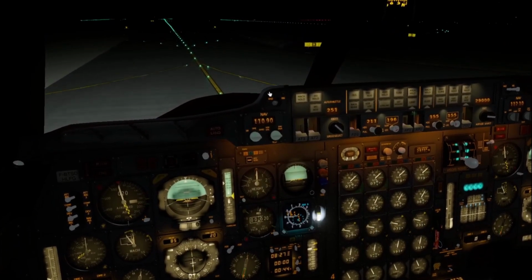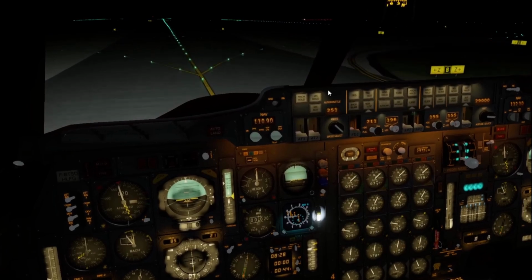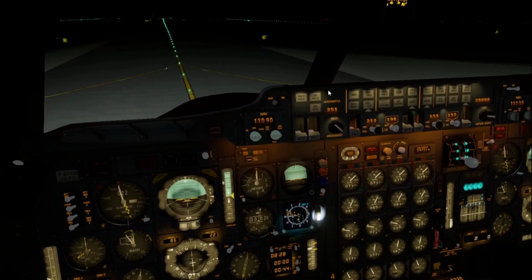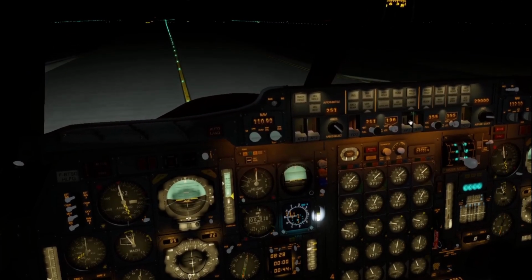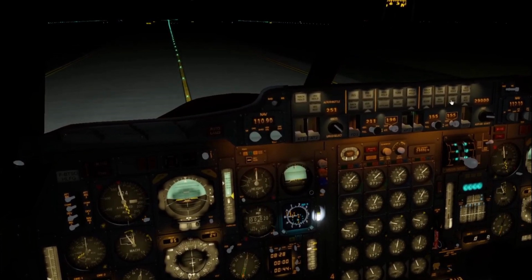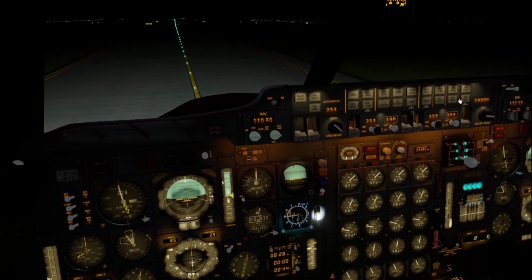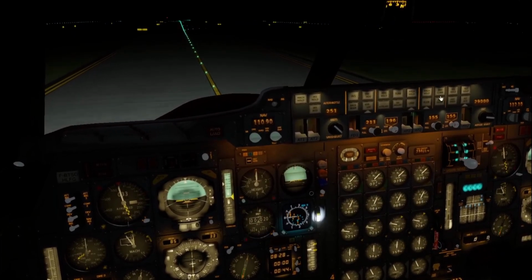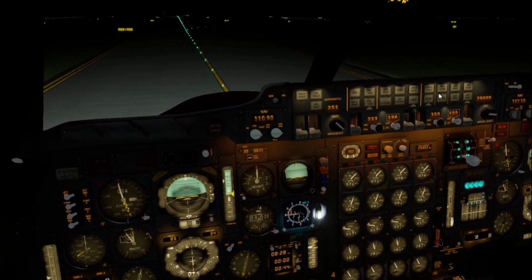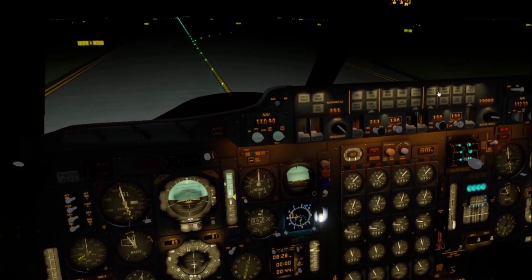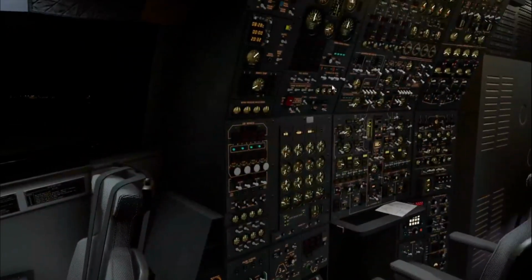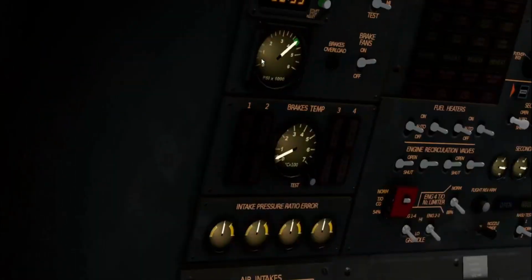After takeoff, I'll set it on, and it will maintain the basic autopilot mode, which is heading hold and pitch hold. So we'll do this after takeoff. Then we will hit AP1 as autopilot, vertical speed. Of course, you can use pitch hold and max climb, max cruise, but I will not do this. Always watch the brake pressure, temperature. It should not be more than 100.